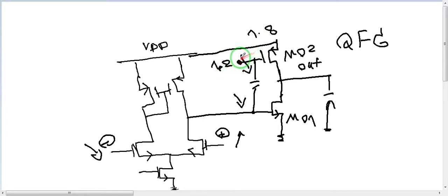So when this one is stable, we have a gate source of like 0.6, and the bias will be limited to this kind of value, but when this one goes down, it is going to be, for example, this is a very high impedance node, so maybe even 0.1. So the gate source will change.